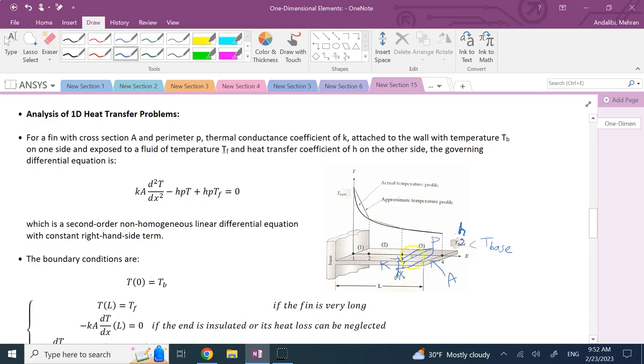And then the heat that is dissipated through the top, the bottom side, right? And the left side and the right side, and then there is a heat that goes out of the right face, correct? So this is your element. And as I said, there is some heat coming in through conductance, some heat going out through the conductance, and then it is dissipating heat to the fluid through what? Through these 4 red arrows. Let me use a different color so you see the difference here. So the greens are the conductions and the reds are the convections.